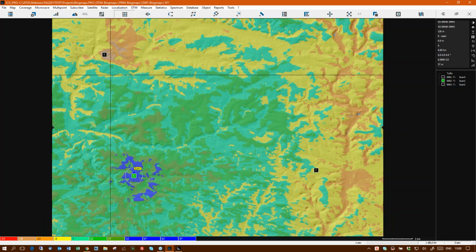Now the other thing, of course, is that you may wish to deliberately degrade this base station from this base station, and you want to know where you can deliberately degrade it. So that's a useful way of knowing where there's enough degradation for you to be able to program your equipment to perhaps swap from one base station to another at a particular threshold, that sort of thing.